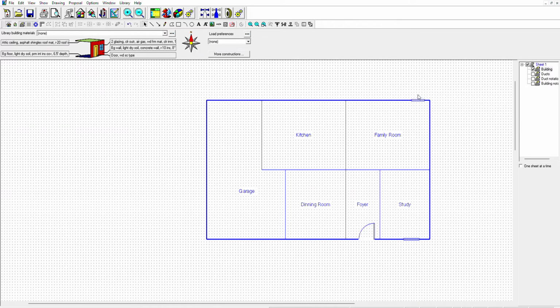And then see, there is also another option, so you don't have to go back and forth all the time selecting. There is an option that you go to drawing, proposals, show. It says repeat last selection.